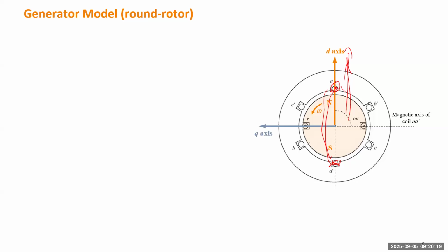So for this picture, the flux has no coupling with the winding because it's in parallel with the winding. Which means if we turn the rotor back 90 degrees, so when the N axis is pointing in this direction, the flux is fully coupled with A, right? So in this direction, 90 degrees before, you have the maximal coupling of the rotor flux with stator winding A.